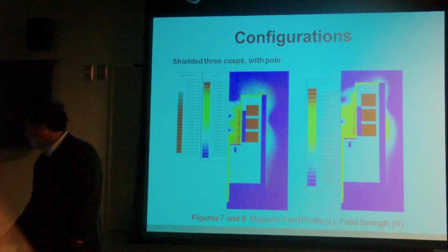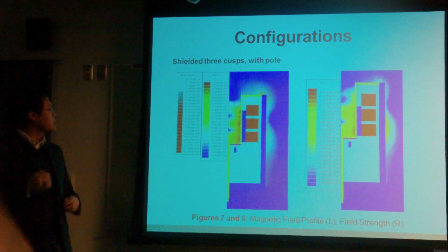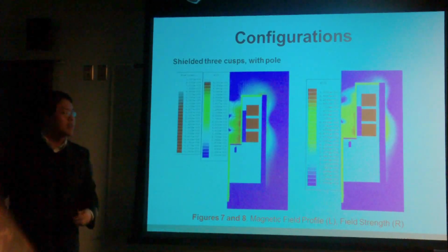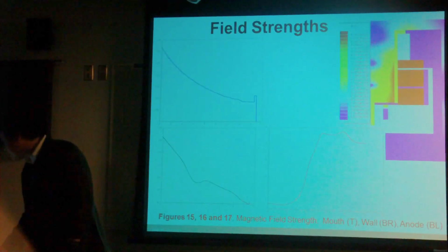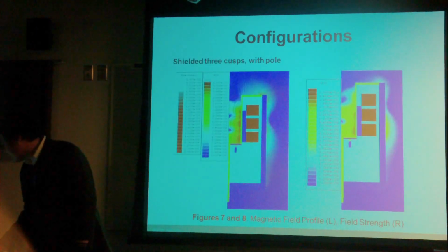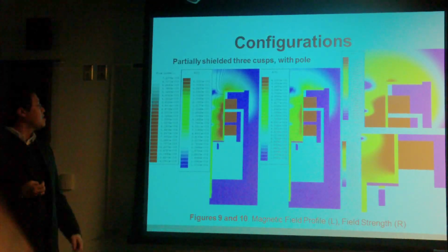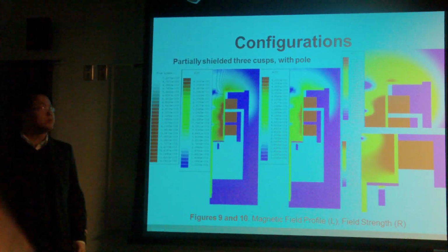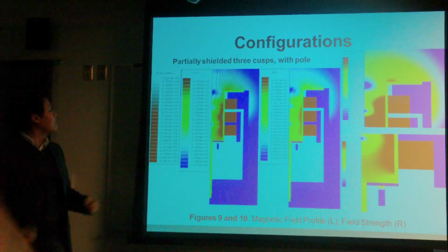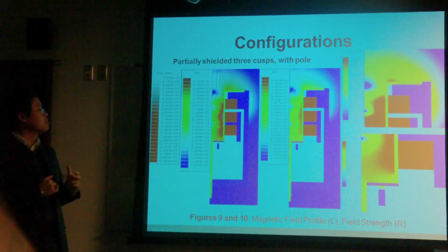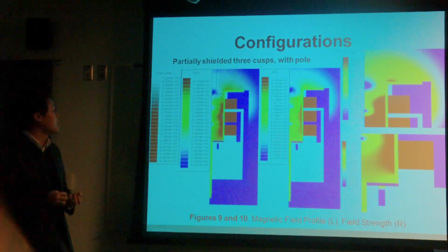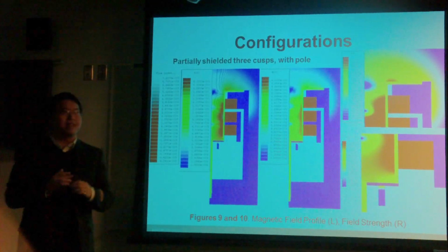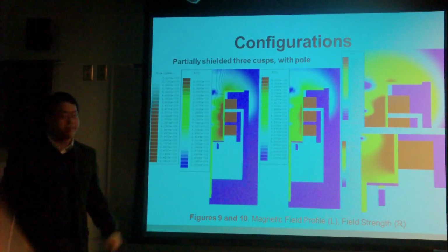So moving on, we tried even more designs, and they were getting closer and closer, but there is still a discrepancy between the flat separatrix and the field strengths, which had to be addressed properly. So this was a design that showed some promise. We were able to drive the separatrix as near to the mouth of the thruster as possible, but we still had the issues of the weak field strengths. And we also had the issue of the thruster still not being a comparable size with Dan Courtney's design. So we went through several iterations with various different sizes for spacers, magnets, etc.